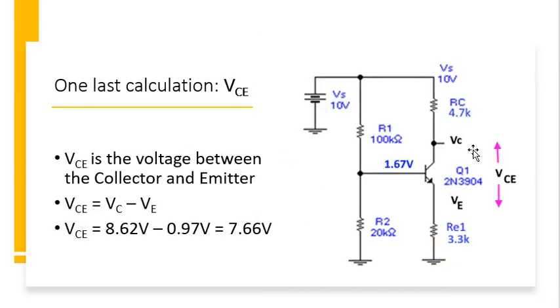So when it's an analog amplifier, what we want is to have on the collector a voltage swing. We want to put a signal on here like a sine wave. In order to do that, we have to have some voltage that it can go positive and some voltage that can go negative. If it was just 0.2 volts, we couldn't go anywhere because it's stuck at 0.2 volts. Here we're actually going to be able to ride an AC signal on top of this DC voltage.